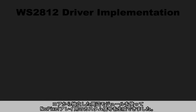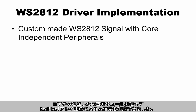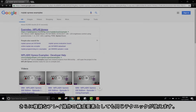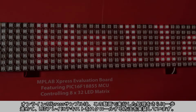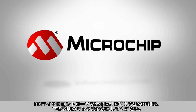Through core independent peripherals, we were able to create a custom signal for our Neopixel array. This hardware implementation greatly reduces the amount of responsibility on the CPU. The same technique can be used as a building block for more complex array manipulation. Express examples online show how to take what we did in this video a step further to implement scrolling text on this 256 LED array. For more information on using Neopixels with PIC microcontrollers, please see the link provided in the description below.